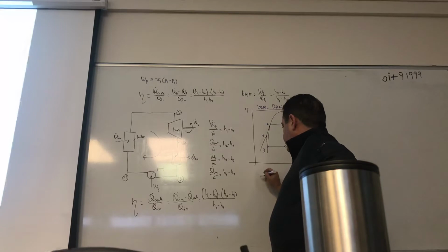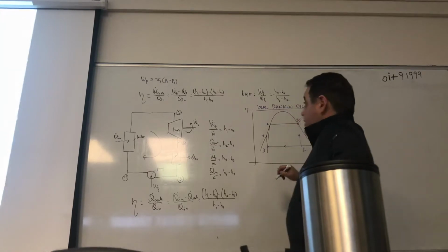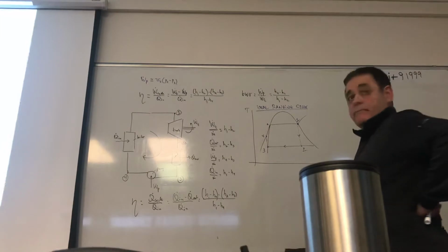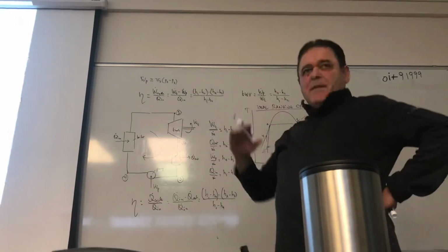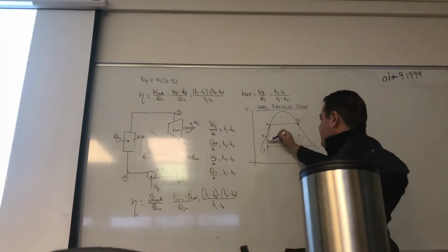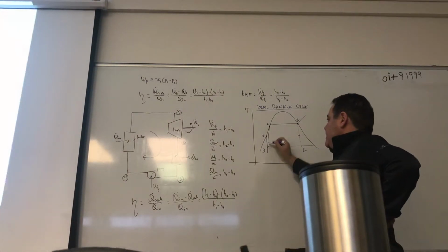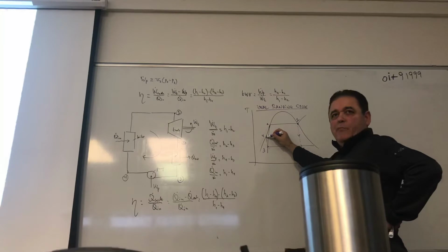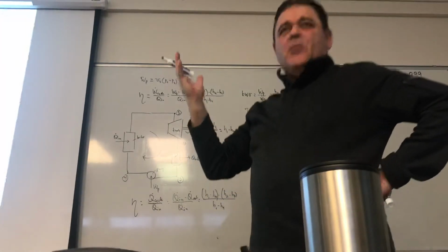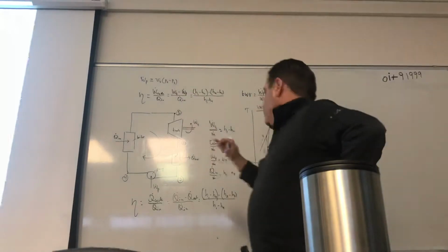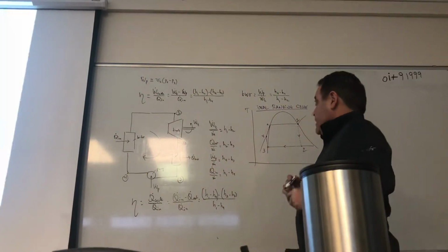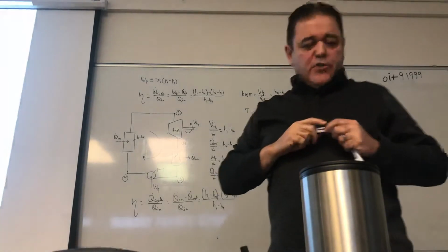P4 minus P3, yes. Work of the pump is approximately that. Why? Because between here and here, the V is there, but here it gets more compressed. Technically it's less, but really it's liquid. So we just use the value of V3 and multiply it by the pressure difference.